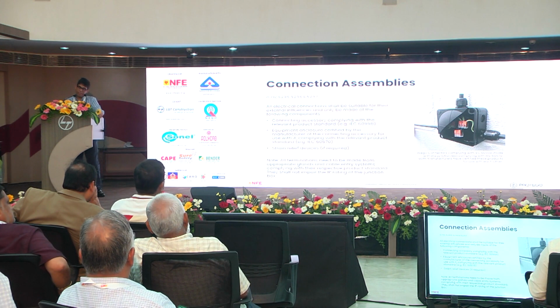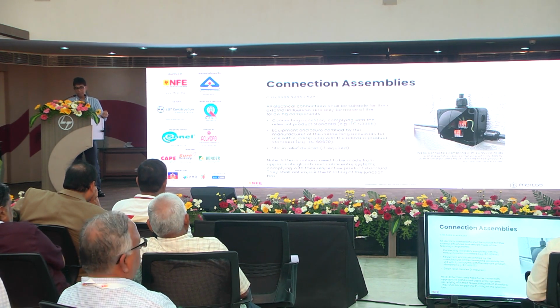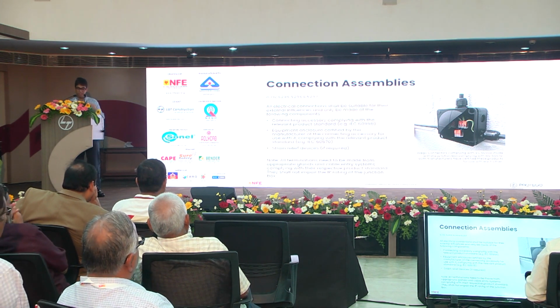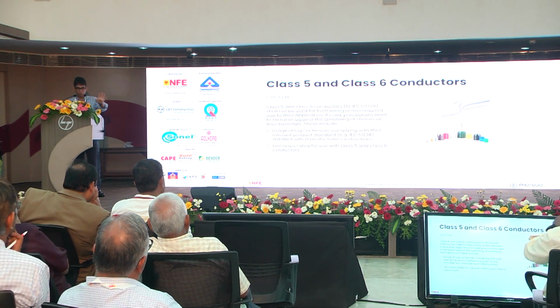Strain relief devices are important because say there is a strain on this cable, what is going to happen is the termination is going to get strained. So strain relief devices, sometimes they are built inside glands, sometimes they are not, need to be there so that at the end of the day, when there's a strain on the cable, the termination is not affected. Obviously, the cable has to be built to withstand that strain.